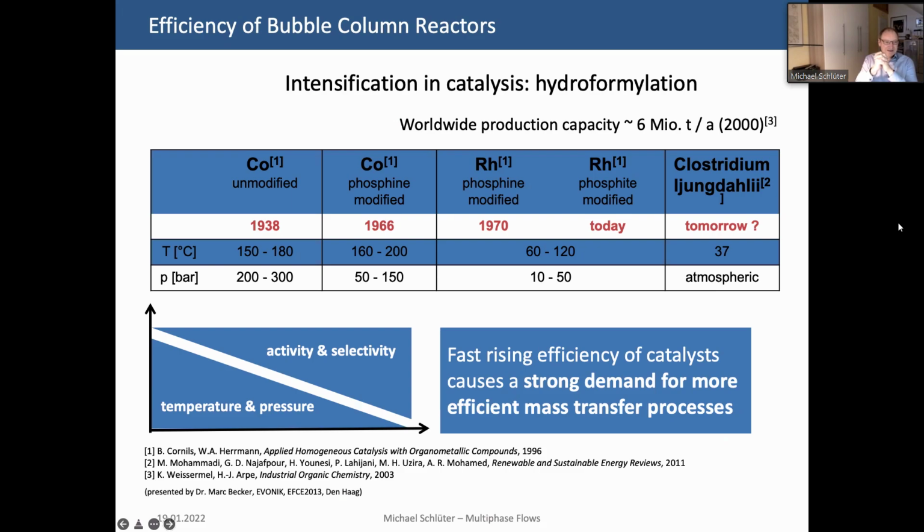performance as well. Yeah, the reaction itself is a sink for our raw materials, for our educts. And if the reaction gets faster and faster, and this will be done by nanotechnology, biocatalysis, and so on, so more efficient catalysts will be developed in future. This means the sink where the reaction takes place is much, much stronger. But what does it mean? This means that even more educts have to be transferred to the catalyst, and vice versa. The product has to be transferred away from the catalyst.